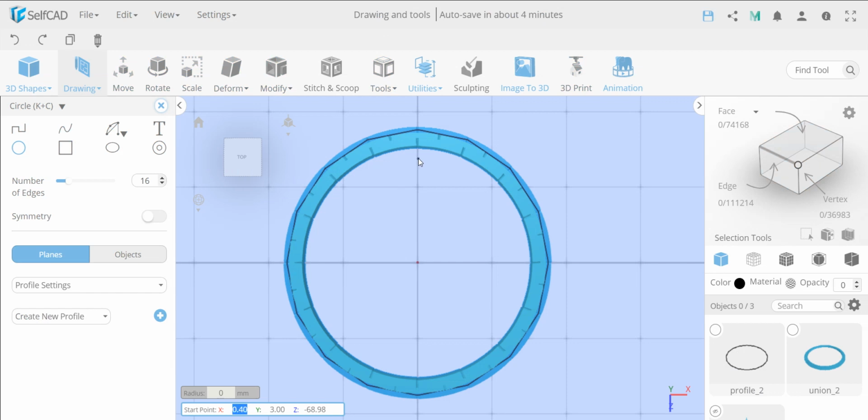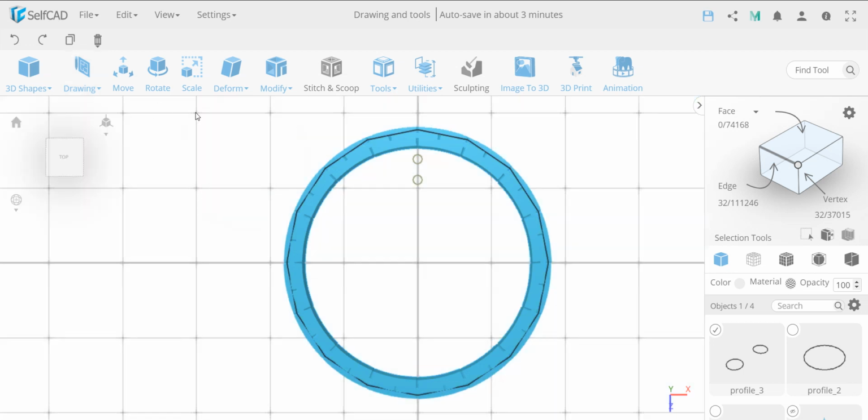So what we're going to do now is, I didn't measure the distance from here, I'm just going to eyeball it, and I'm going to put in a circle, and type in, let's say 3. Let's make it a nice circle of 3, and then I can actually measure the distance between them. I should have probably, but for now that should be fine. So I'll make 2 circles of 3. Actually, this is too close to each other. I think the design called for them a little bit further away, but not too far away, because then they'll start intersecting when I pivot them around. So let's say 3. Okay, so I got these 2. Now let's see how I can pivot them around.